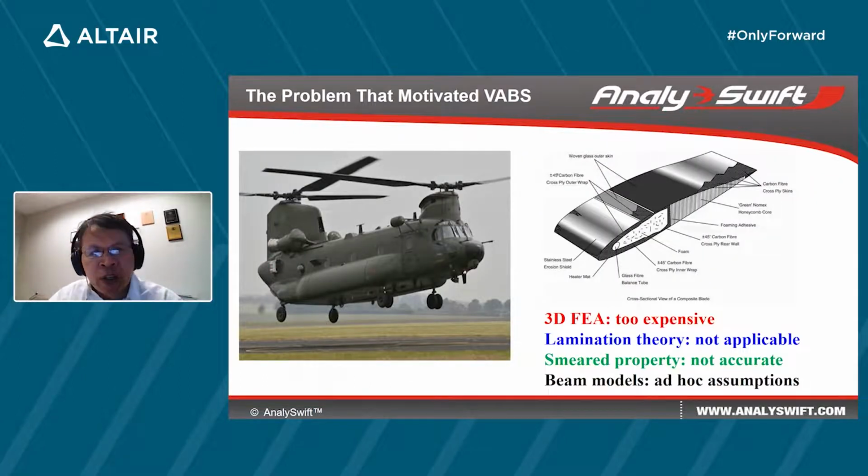The WEBS technology was motivated by the need of the helicopter industry to provide an engineered solution for composite helicopter rotor blades. The rotor blades are made of composites because of the excellent fatigue performance of composite materials. A typical rotor blade could be several meters long and half meter wide.